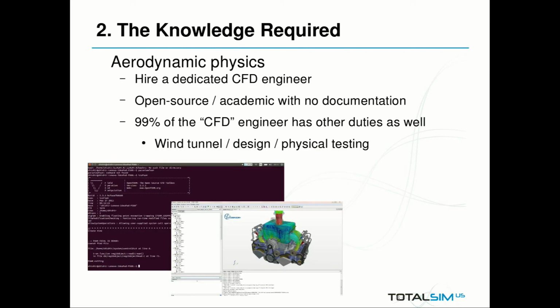Also, when you want to do a CFD simulation, you're going to need quite a bit of engineering background and have probably taken several courses on how to perform CFD simulations, because it requires a base knowledge of how to mesh the geometry, what boundary conditions you need to set up, and what solver settings you need to get the turbulence conditions you want.